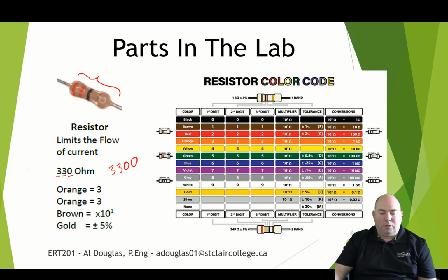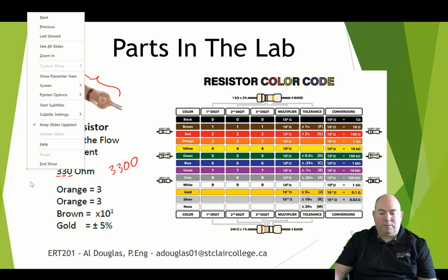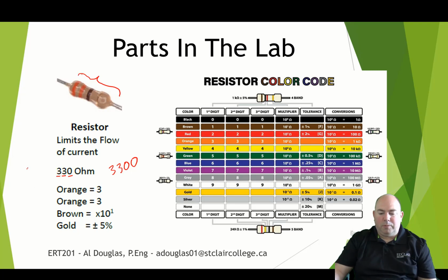So you can expect that you'll be within 5% accuracy on this. I think that 5% of this is about 15 ohms. So this should be anywhere between 315 to 345 ohms if you were to actually measure it. It will guarantee that it'll fall somewhere within there.